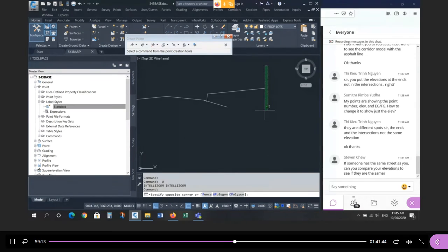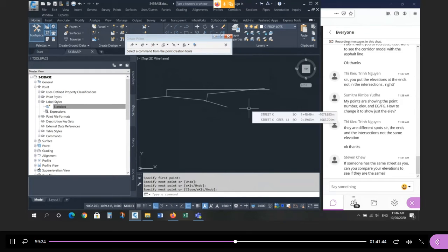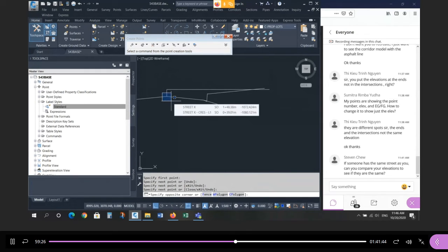Okay, so what that means now is, what's the elevation at the front lot corner going to be in the future? And the rule of thumb is this: from the existing center line, we're going to go up 0.3 of a foot, and that's the elevation we want to use at the street line. So whatever the existing center line elevation is today, I'm going to use that number, add 0.3, and that's the proposed street line elevation. And that'll be compatible to the urbanization of the rural road to an urban section in the future. Does everybody understand what the design requirement is?